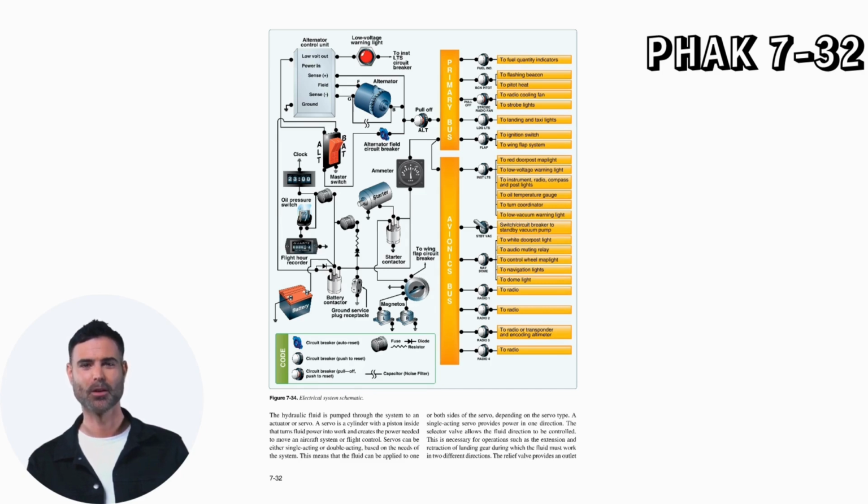Servos can be either single-acting or double-acting, based on the needs of the system. This means that the fluid can be applied to one or both sides of the servo, depending on the servo type.